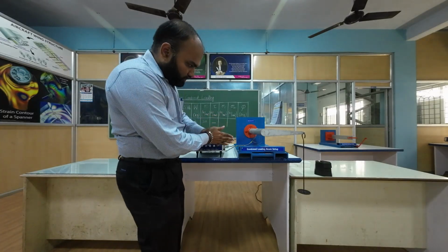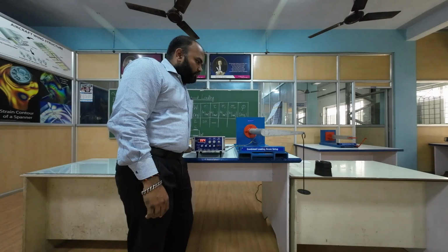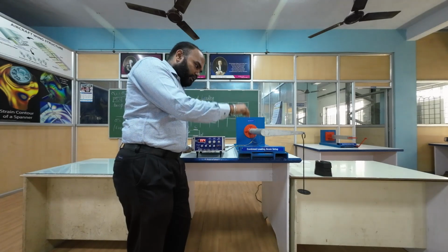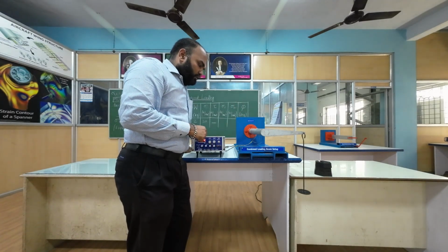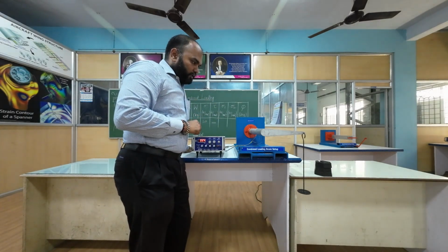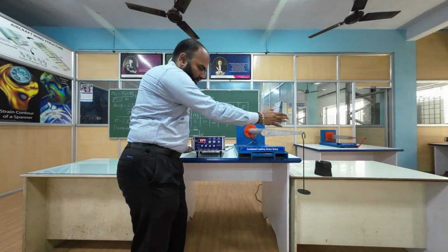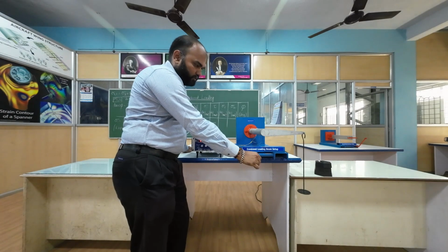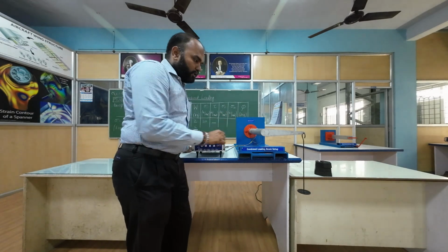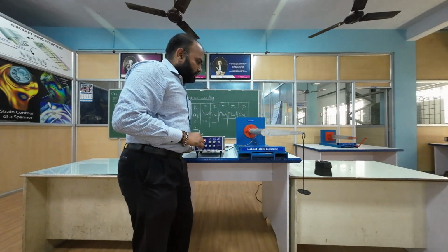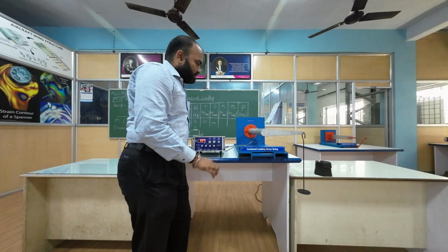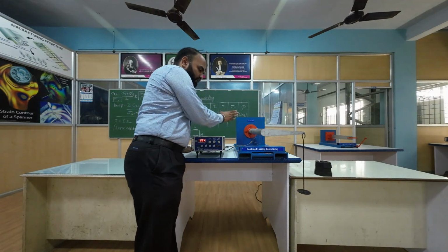So this is a setup for combined loading. For this beam, we have combined loading, which means direct bending and then torsion. We have a cantilever beam of length 554 mm, and then an extended arm. If you apply load directly here, it is going to cause pure bending. If you have an arm and apply load at that point, it is going to cause bending plus torsion. This is of 3 mm thickness, and to measure the required parameters, we have 3 strain gauges located at 3 different locations.